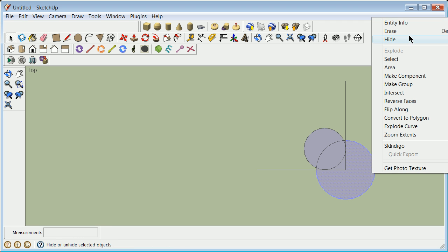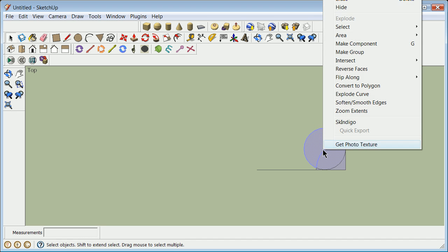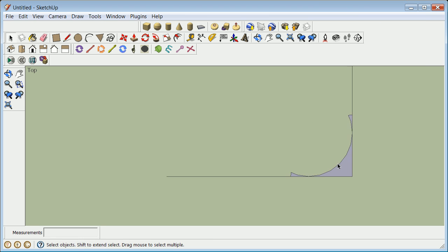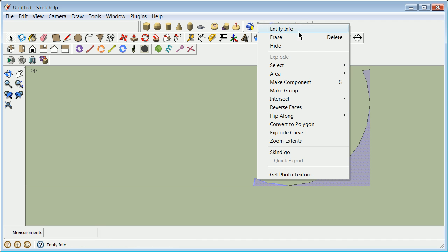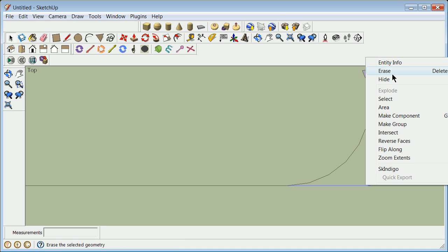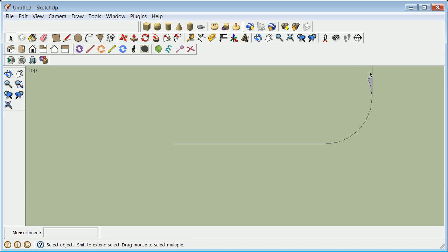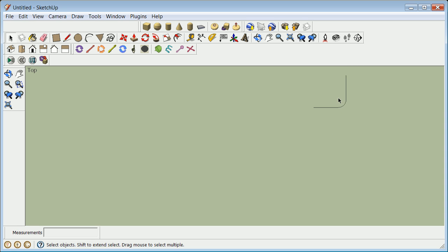So learning how to do fillets comes from knowing how to grab things off the web. There's going to be a Ruby that'll do a fillet for us. So we're going to see whether that in fact took, and at this point our expectation is that this is not a perfect fillet, because you see how SketchUp makes things in little straight lines. But we have our alignment there.